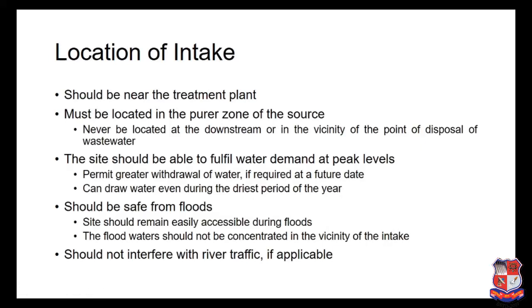It should be safe from floods, right? The site should remain easily accessible during floods. So the intake should not be submerged during floods. It should remain accessible during the flood also. So the height of the intake should be decided by checking the HFL, or high flood level, in the reservoir, or we can say in the river.